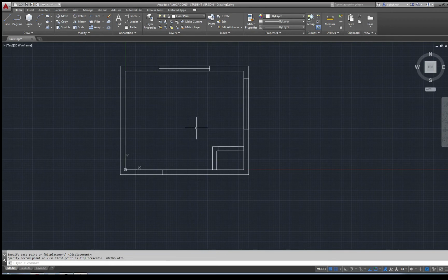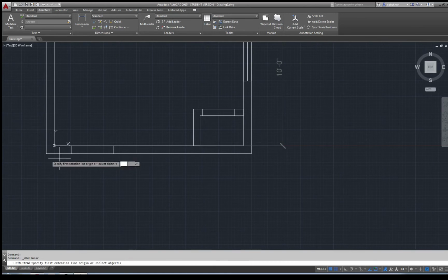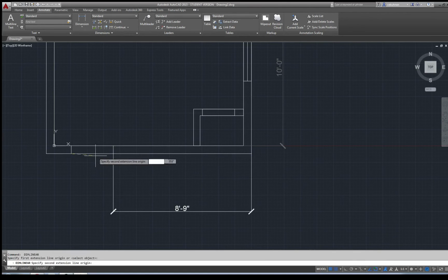So I hope this, for example, so far nicely illustrated how we can quickly create a very basic floor plan with those drawing tools. Let's take a look back at our dimensioning. For example, maybe I would like to add some more. Let's go back to annotations. So for example, I have points turned off. So for example, this to this. For example, I would like to see as a readout this one to this one.